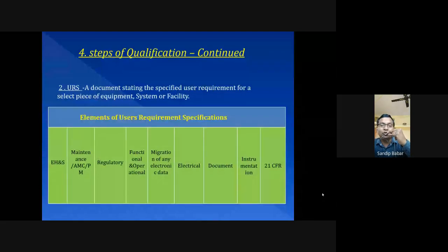We have to decide what is the DO range, pH range, RPM range, airflow requirement range, oxygen flow requirement range, what is tip speed required, what is P by V, power by volume, required, what is the headspace required, how many exhaust or how many inlet filters required, what is the temperature maintenance band required. These are all operational requirements we have to consider during preparation of URS.